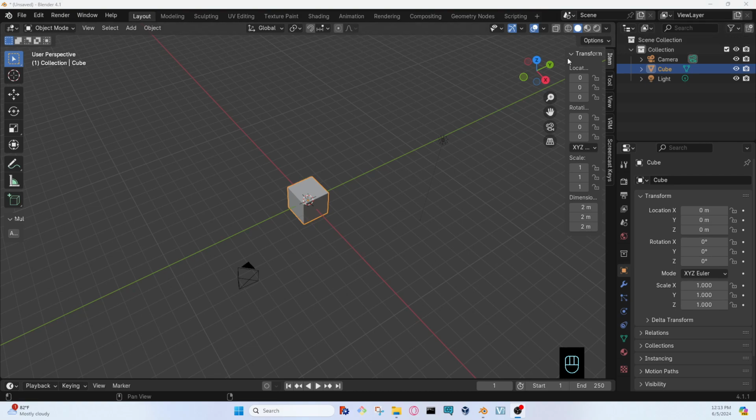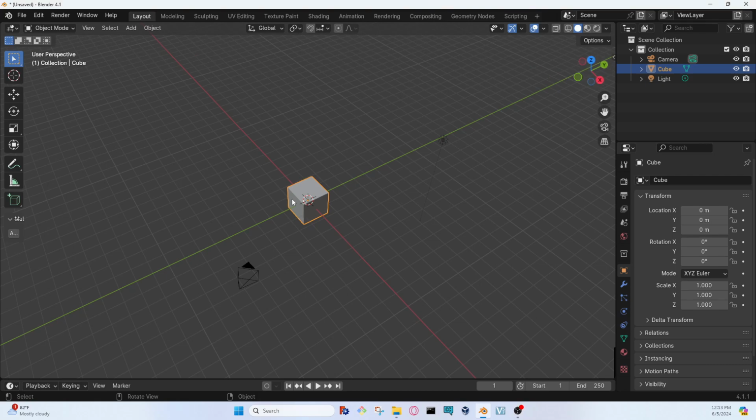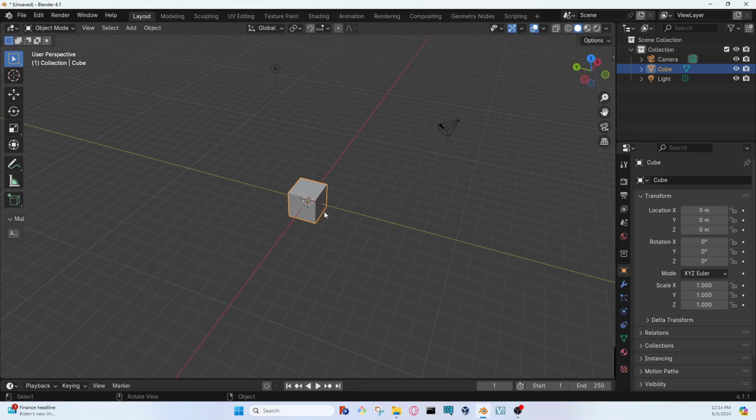You can also rotate by doing the same thing that we did before with the scaling. You can snap it to that axis. So we can hit R for rotate. You can snap it to the Z axis. You can rotate it on the Z. You can decide to rotate it on the Y axis. And you can decide to rotate it on the X axis simply by pressing the axis hotkey that you want to rotate it on. And again, if you decided that was the wrong movement, you can right click off to stop.